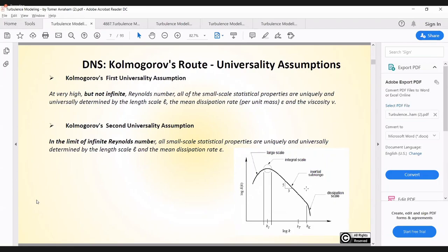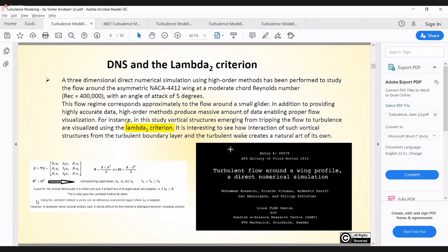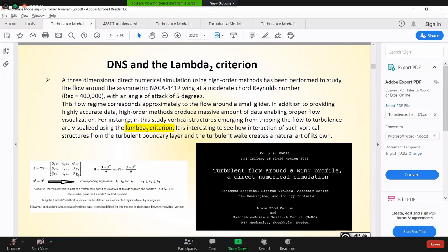With the Smagorinsky model, it had this problem. Sometimes you cut it, or there was a time they tried a method called very large eddy simulation. What happened with very large eddy simulation is that you got a line going like that, and it doesn't work. Here you see what I've explained about the velocity gradient tensor.